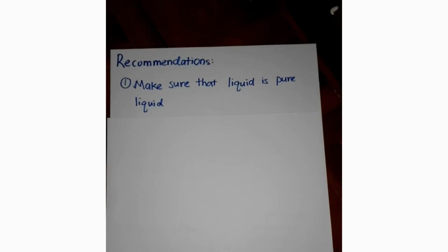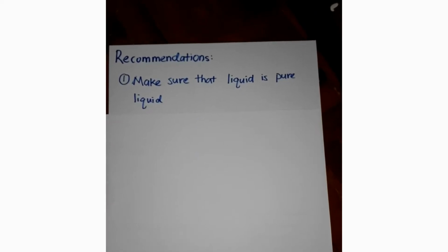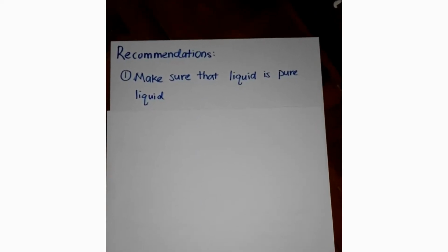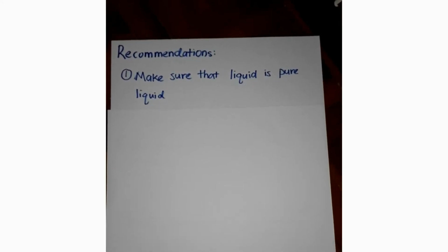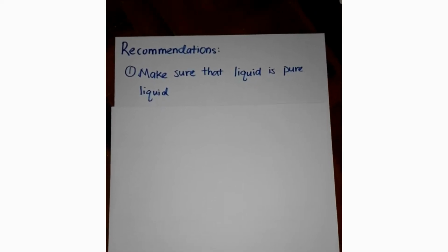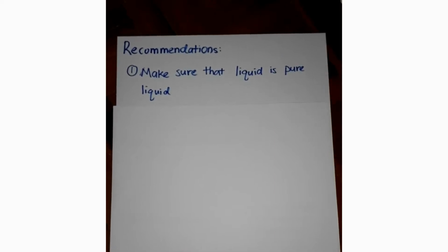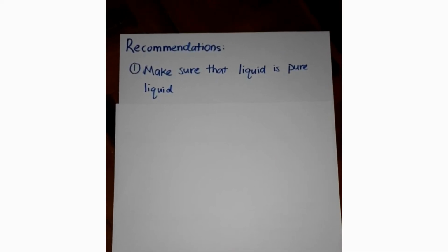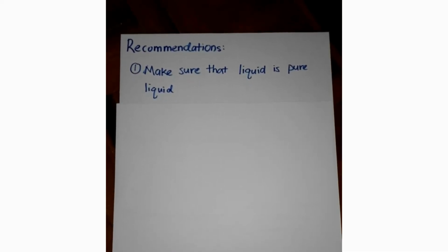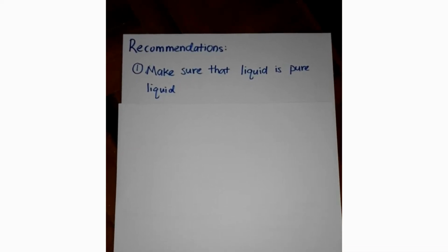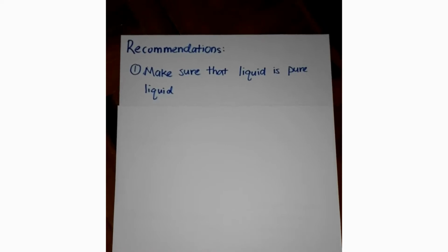This is because when it is a multi-component solution, the light component will evaporate first, and then the micro layer enriches in heavy component, which will cause the boiling point of the micro layer liquid to increase. Consequently, the boiling heat transfer coefficient would be reduced in comparison with pure water or pure liquid.